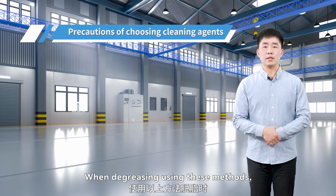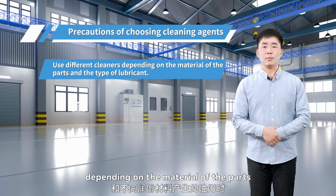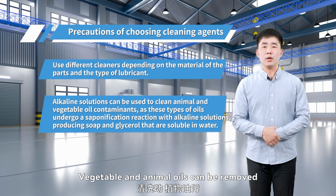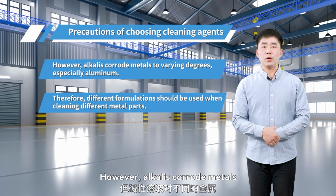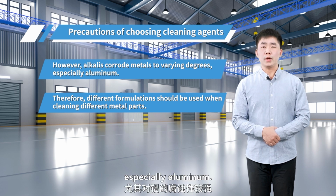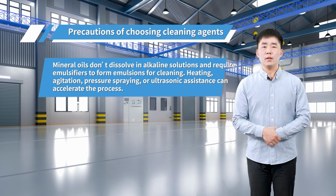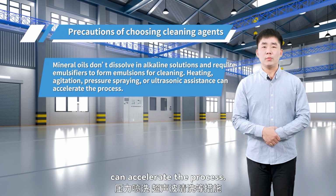When degreasing using these methods, proper cleaning agent selection is key. Use different cleaners depending on the material of the parts and the type of lubricant. Vegetable and animal oils can be removed using alkali solutions. However, alkalis corrode metals to varying degrees, especially aluminum. Mineral oils don't dissolve in alkaline solutions. When cleaning the mineral oil stains on the surface of the parts, it requires emulsifiers to form emulsions for cleaning. Heating, agitation, pressure spraying, or ultrasonic assistance can accelerate the process.